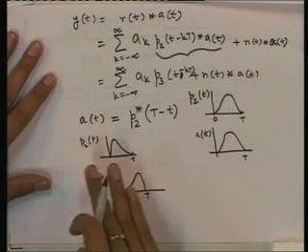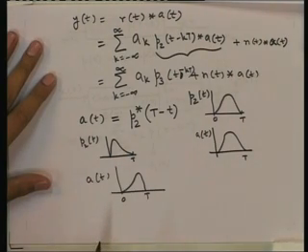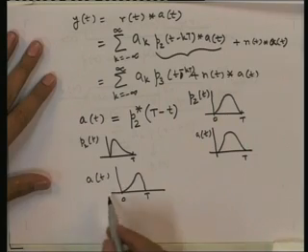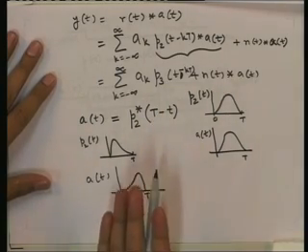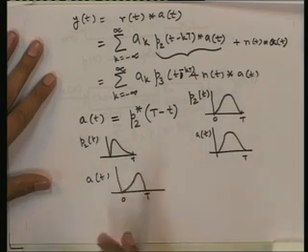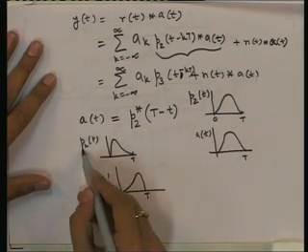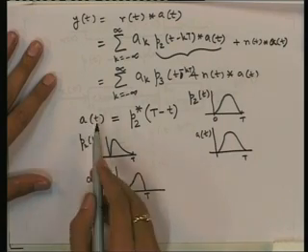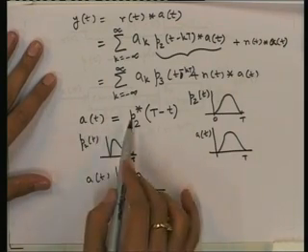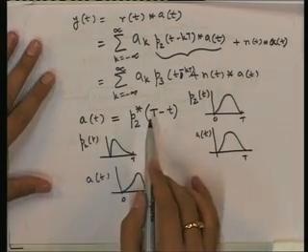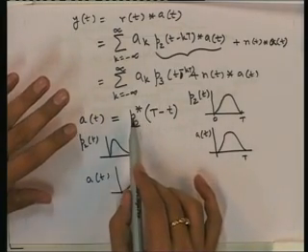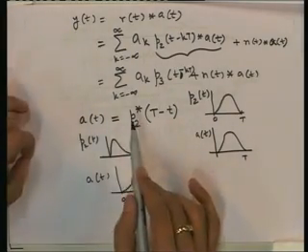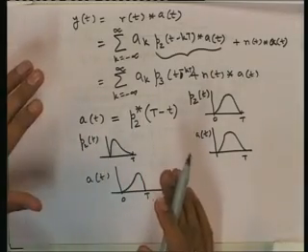It will be flipped. So we see what it means to do this. Capital T minus t means basically flipping: 0 comes to T, T comes to 0. So this is called the matched filter. A filter with this impulse response is called the matched filter to this pulse. A filter matched to the pulse p2(t), that is the matched filter.